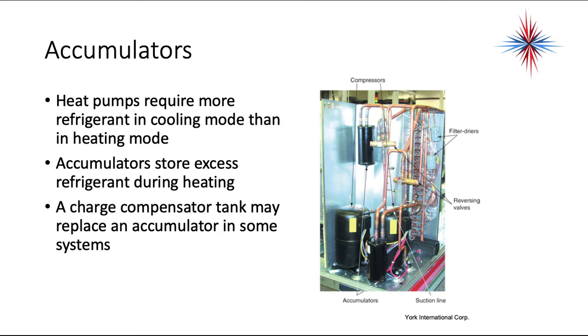The reason for the accumulator is that heat pumps require more refrigerant in the cooling mode than in the heating mode. Accumulators also store excess refrigerant during heating. A charge compensator tank may replace an accumulator in some systems, rarely. What the accumulator does, it allows liquid refrigerant to sit without getting into the compressor.